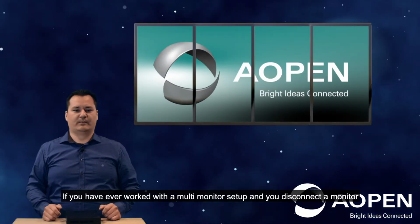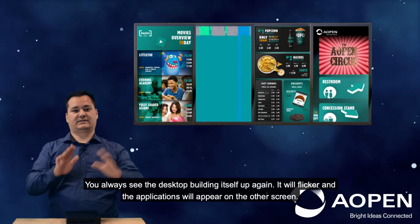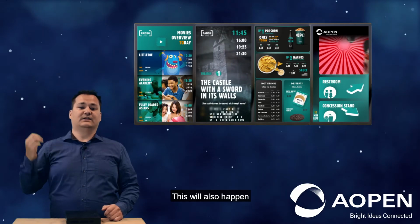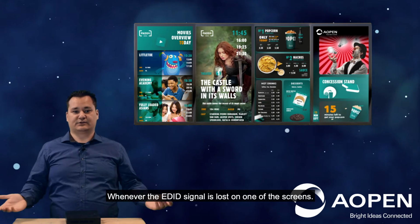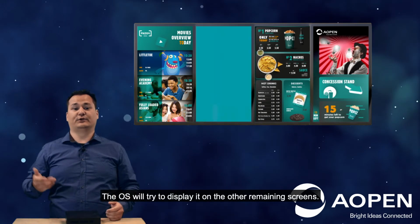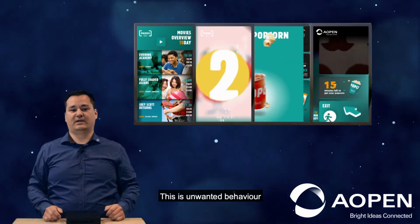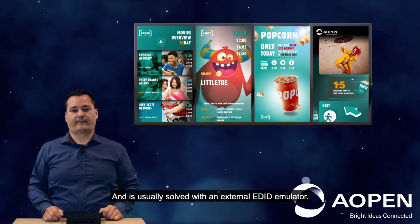If you have ever worked with a multi-monitor setup and you disconnect your monitor, you always see the desktop building itself up again. It will flicker and the application will appear on the other screen. This will also happen with the same video wall. Whenever the EDID signal is lost on one of the screens, the OS will try to display it on the remaining screens. This is unwanted behavior, and is usually solved with an external EDID emulator.